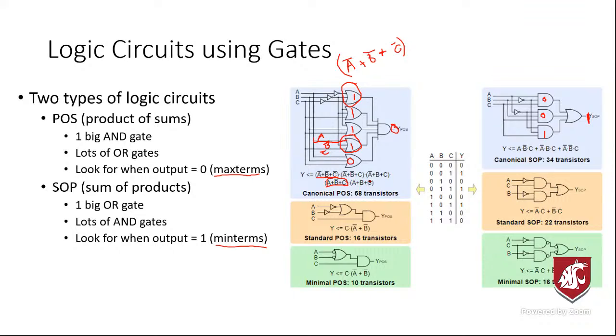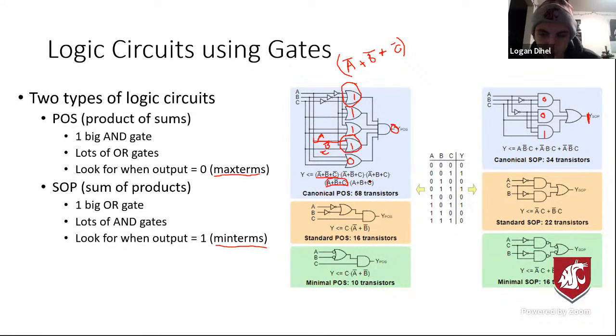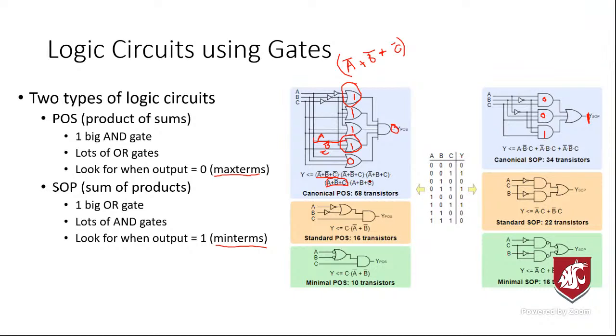Yeah, so you want to convert the SOP equation to a truth table, which will make it easier to simplify. Exactly. You need to get it to a K-map to perform the simplifying process. So you should always try to, if you start with a truth table, put it into a K-map. If you start with a circuit or an equation, then convert that into a K-map. And then once you have a K-map, you just perform the normal rules and find the final minimized equation. So yeah, the K-map's basically the key.